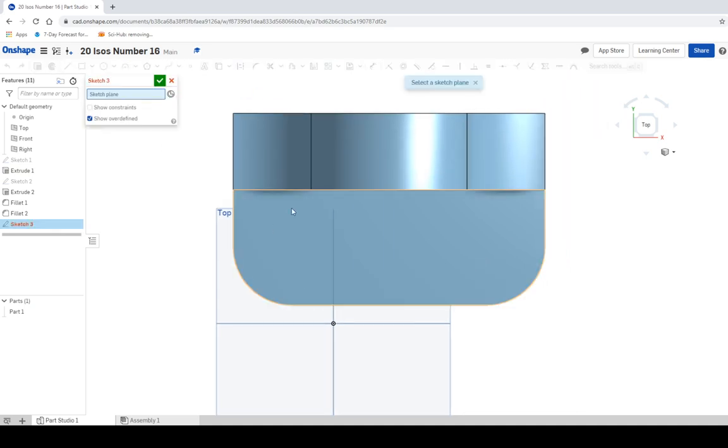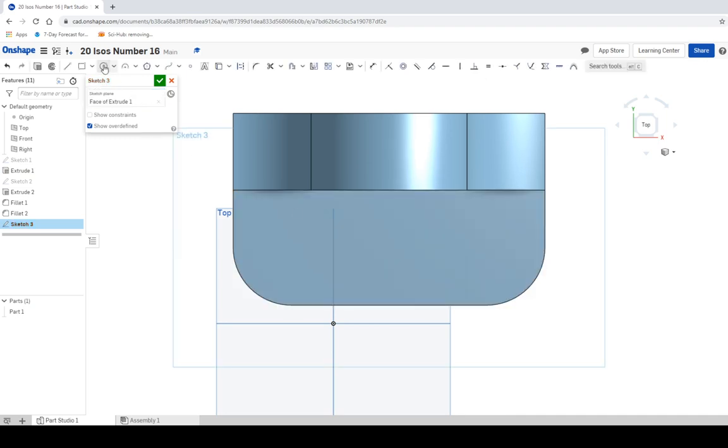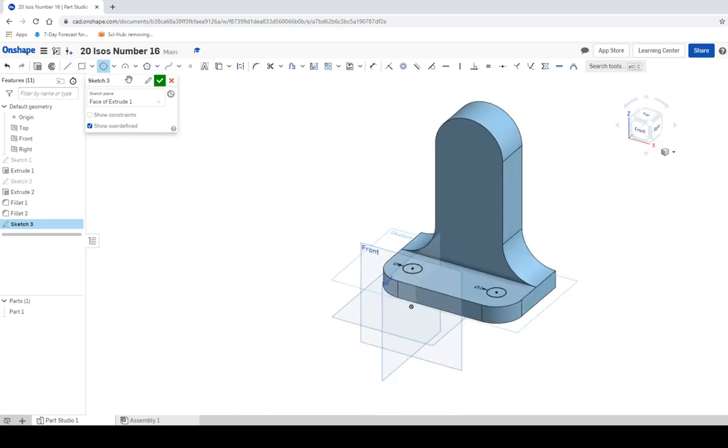So I'm going to make a sketch on the flat part of the shape. I'm going to click the circle, and this circle is going to, remember, move over to the edge of the fillet and then move your mouse till it snaps into place. It's going to be the edge of your circle. These holes are going to have a diameter of 1 inch. So we're going to make a diameter of 1 inch for both, and move back to an isometric view,